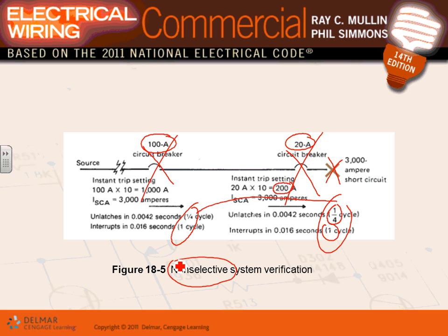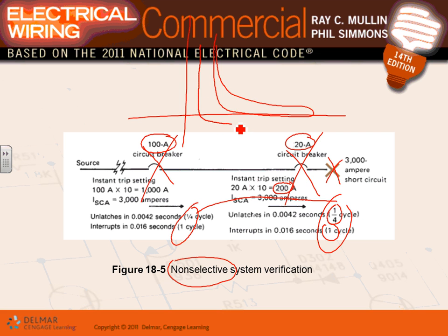Next week, guys, you're going to see a curve. Instead of looking at this, there's a curve. You have two curves. If the two curves touch each other, bad news. Here's a curve of my circuit breaker 1, and here's a curve of the other circuit breaker. Can you see that? If they're touching each other right in this area, this means they will trip at a certain value. That's what the coordination is all about. You don't want these time current curves to touch each other.